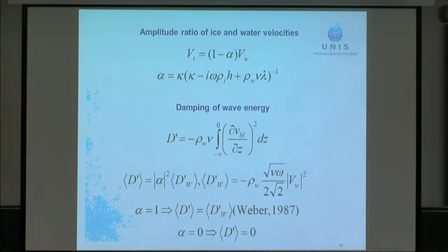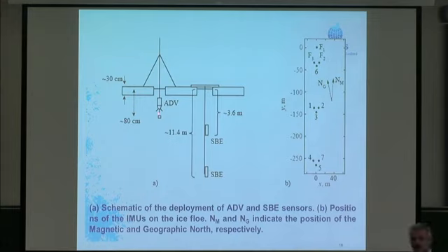So how can you use the acoustical device for measuring all these three directions? Usually you have one direction. Usually we use a wire anemometer for this. Here we have a transducer, and that transducer sends an acoustic signal. And here we have 3 receivers which get signals at different angles. It is a 5 megahertz acoustic signal. And the receivers know when they should receive the signal, so they are sure that it came from this point. Since we have 3 reflected signals, we have 3 components of velocity.